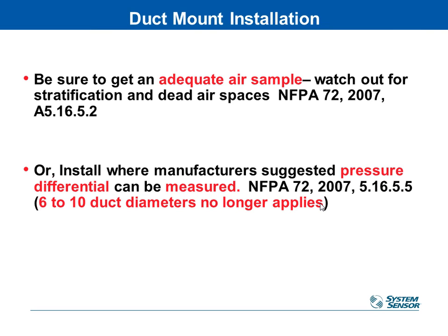And then you could obviously use a manometer or a magnehelic gauge to actually measure those. As a rule of thumb, when you're hunting for that spot that's going to give you good airflow, if you follow the duct diameter rule, the old, get at least 5 duct diameters, or in this case, it's showing you 6 to 10 duct diameters away from stuff, the air will be more stable. If you start looking in those places and then use your manometer to measure that you're getting a good airflow rate, that's probably where you want to start looking.